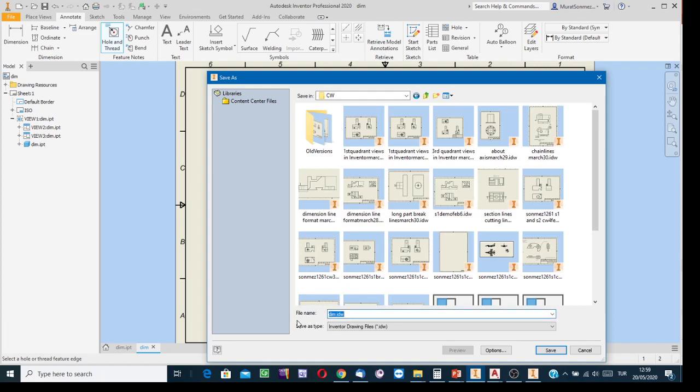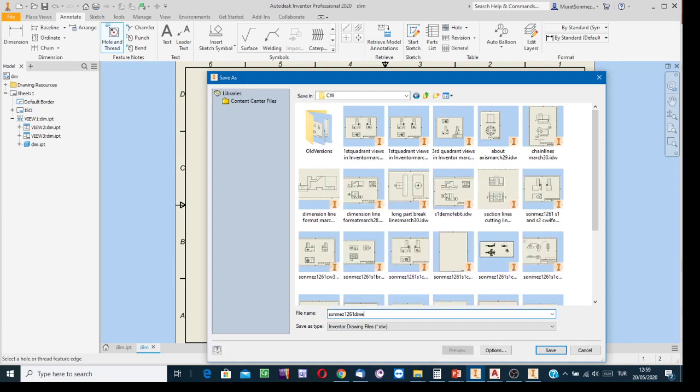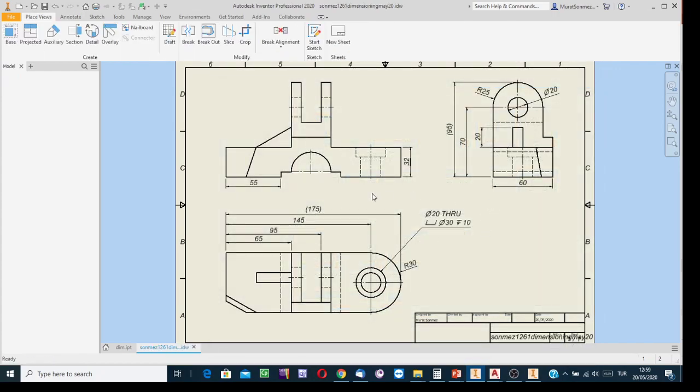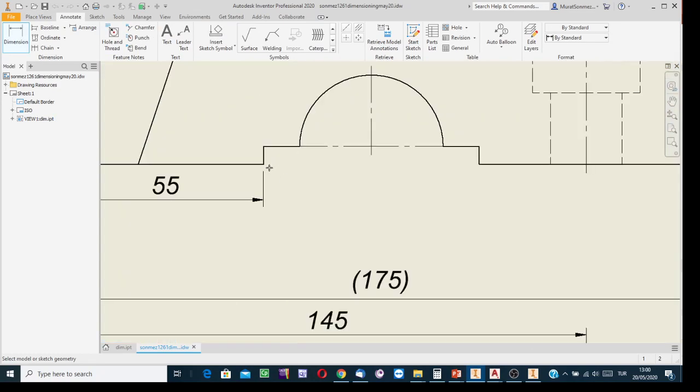Okay, file name, surname, ID number, section number, etc. And it is about dimensioning in Inventor. Date is the 20th of May, May 20. Okay, and then, well, all of such things are non-functional. How about functional dimensions? The channel opening from here to there is a functional dimension. How is it shown? Annotation, dimension, and then indicate the terminal points, and then yes, 60.